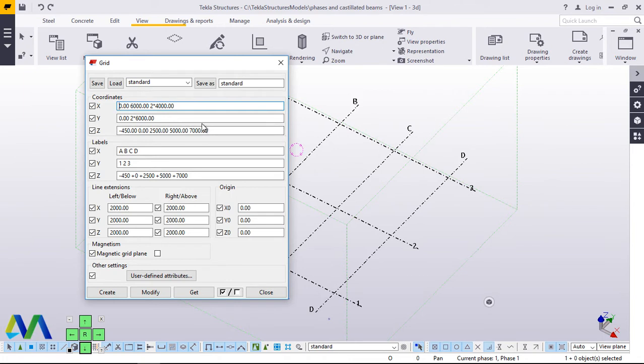And on the x-axis here, I'll feed my dimensions there. I need a 120 span, or I'll change that to 25 columns with an interval of 6 meters. And for the y-axis, I'll feed 8 columns, for the gable beams, with an interval of 5 meters. Now I'll go straight and start that.